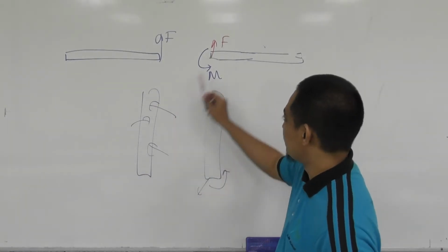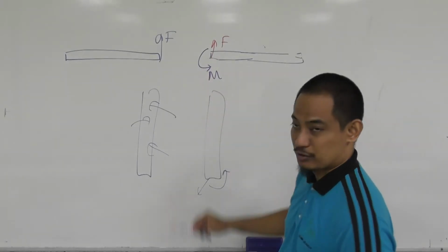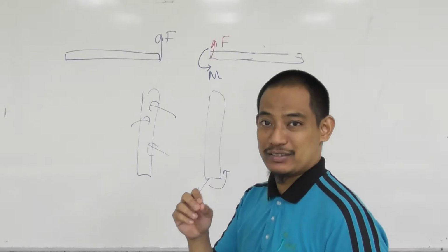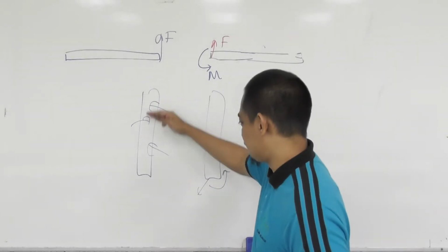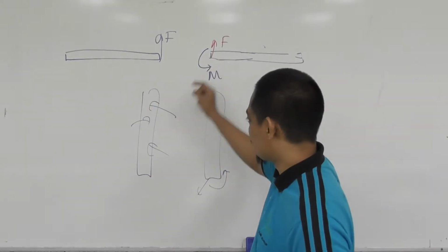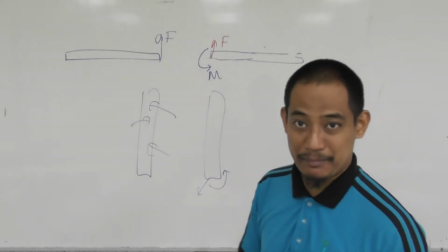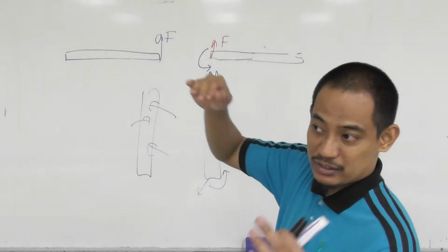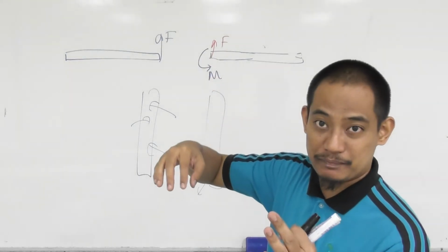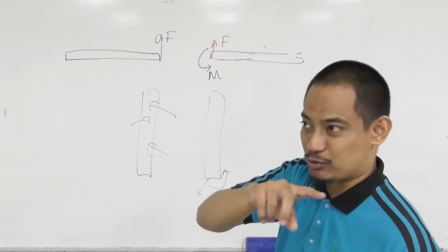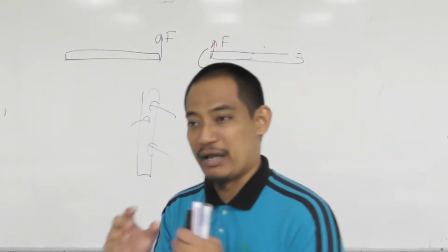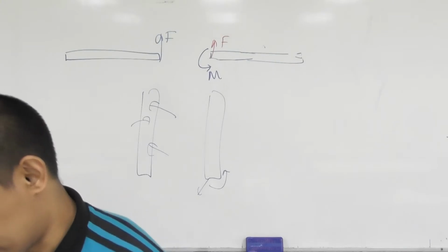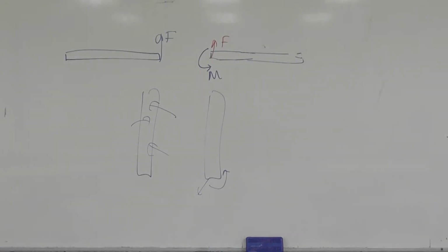But each transfer does introduce a couple moment, so that the net effect is still the same. If you just shift the force without compensating for the moment, the net effect is not the same, because, like we have illustrated here, you are actually cancelling a couple. So you have to introduce the moment, which has the couple effect. So that's the idea.